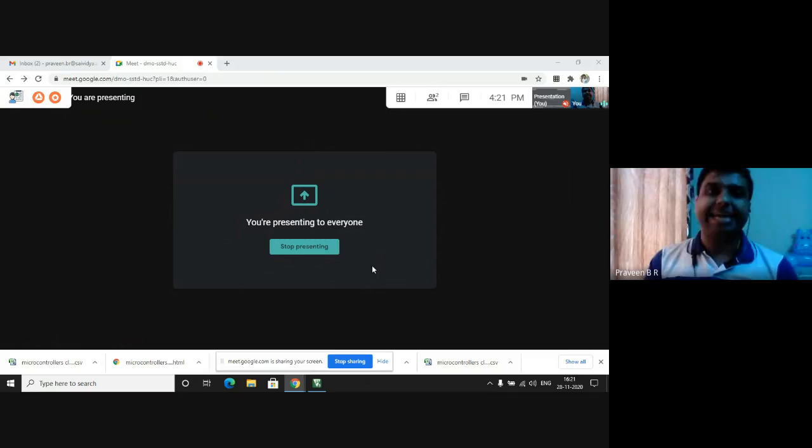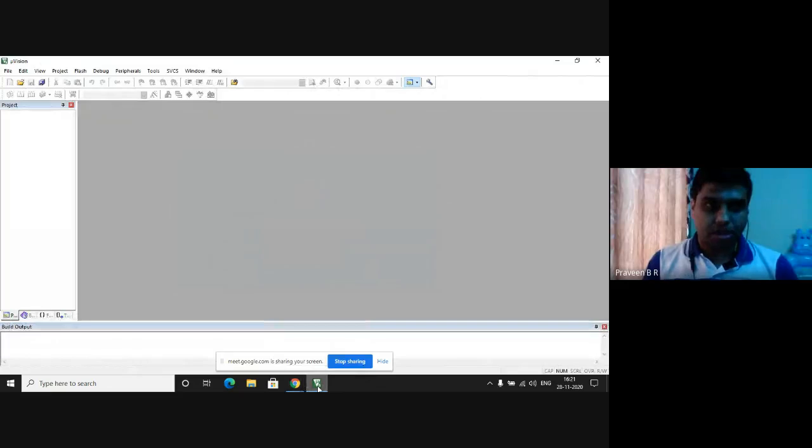The subject code is 18EEL57. So let us study the next program for microcontroller, that is writing an assembly language program to subtract a multi-byte number in two memory locations, one which is there in 8000H memory location and the other number which is there in 9000H memory location, and the resultant will be stored in 6000H memory location. To do this, we'll use the software called Keil MicroVision. In this Keil MicroVision software, let us see how to perform the program.